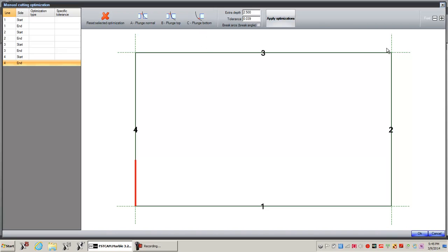I have an outside corner here, and I don't want to waste 5 inches. What we can do with the software is have the blade plunge down on the Z-axis. So instead of losing 5 inches of material, I'll only lose perhaps 1 inch. Again, do I have a 16-inch diameter blade or an 18-inch diameter blade? So, 1 start. This is the end of my slab. I really don't have to do anything here. But over here, I don't want to go out all 5 inches.